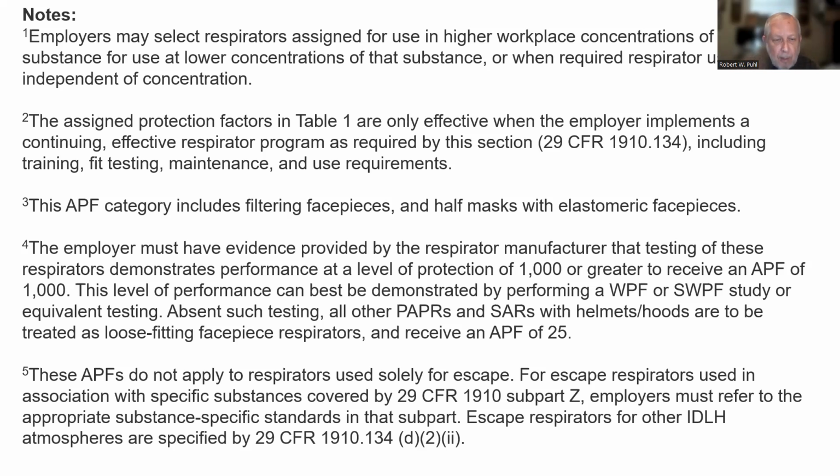These APFs do not apply to respirators used solely for escape. For escape respirators used in association with specific substances covered by 29 CFR 1910 subpart Z, employers must refer to the appropriate substance-specific standards in that subpart. Escape respirators for other IDLH atmospheres are specified by the standard.